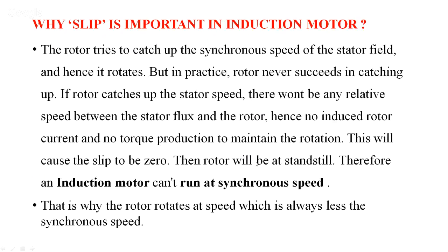Then the motor will be at standstill. So the speed of the rotor starts decreasing and it may come to standstill. Therefore, an induction motor cannot run at synchronous speed. That is why the rotor rotates at a speed which is always less than the synchronous speed. So it will never catch up.